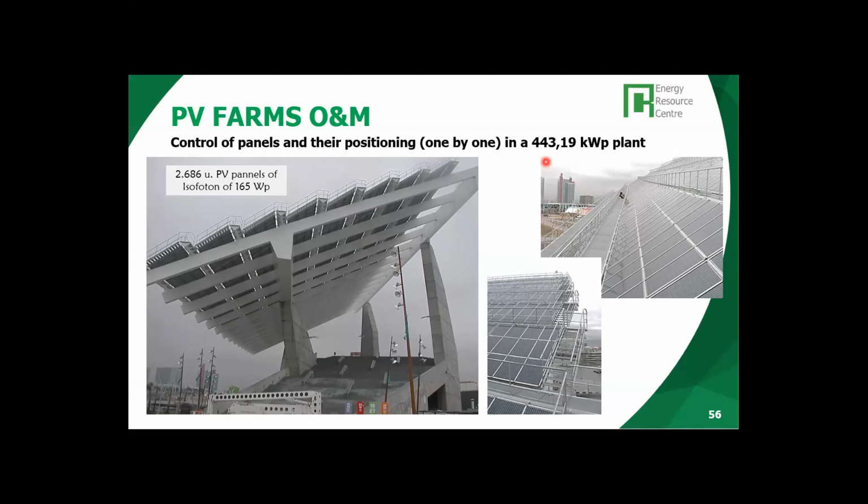Because if we put just one low performing PV panel together with high performing panels in the same string, that string will be affected by the lower output of the low performing panel. So we want to group all the panels performing at the lower threshold of quality together.